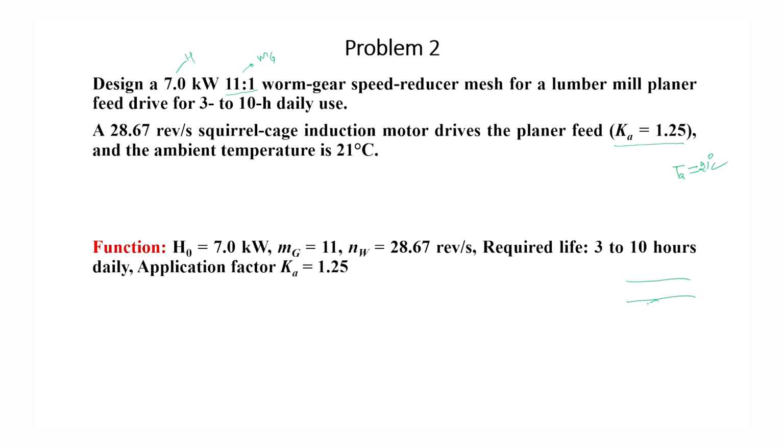of worm and worm gear drive, whatever power input is given, H in, the same will not come out, because due to sliding velocity and loss of power, some of the power will be lost and the H output will be different than the H in, and that will be decided by the efficiency of the drive. The design factor is taken as 1.2.